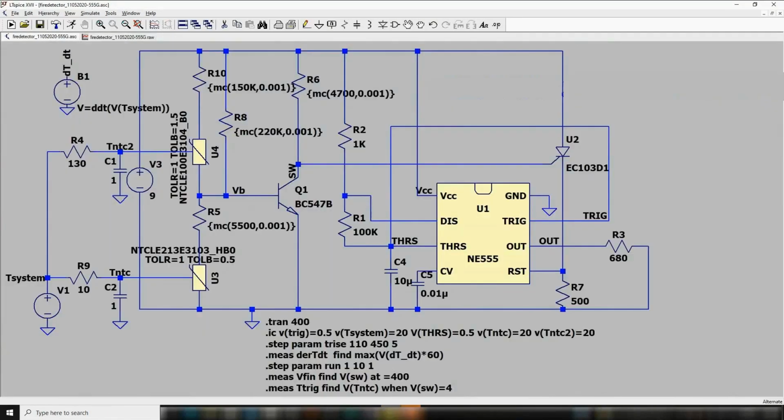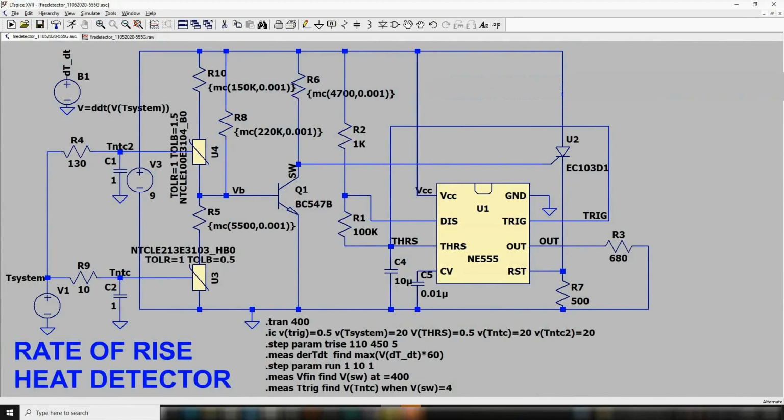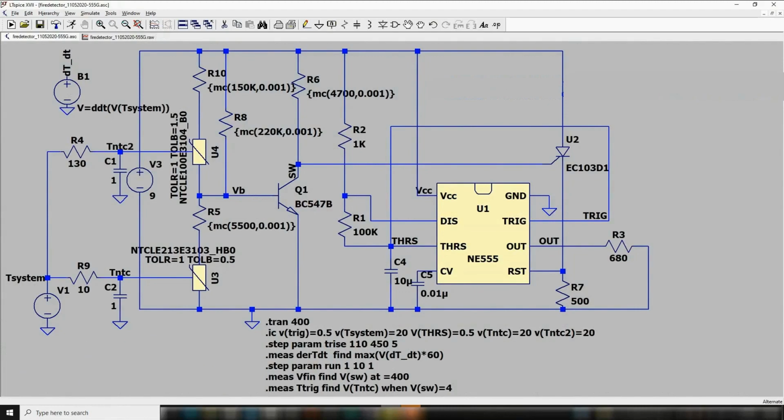So enough for today of this annoying siren buzzer noise. We can go back to a simple detector with one 555 timer, yet with another new feature. The circuit is a rate of rise detector. It will work with the speed of increase of temperature rather than with a fixed level. It contains two NTC thermistors. One exposed which reacts quickly and another protected with slower reaction.